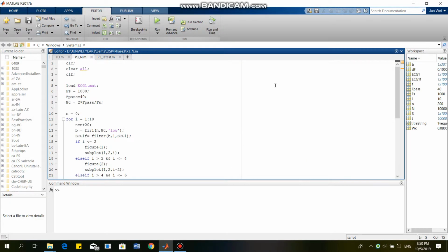From the previous graph, we can see that the signal required is below 40 Hz, thus the passband frequency will be 40 Hz, such that the signal above 40 Hz will be considered as noise. Thus, a FIR filter is required to be designed to remove the noise. A low-pass filter with the Hamming windowing technique is used.